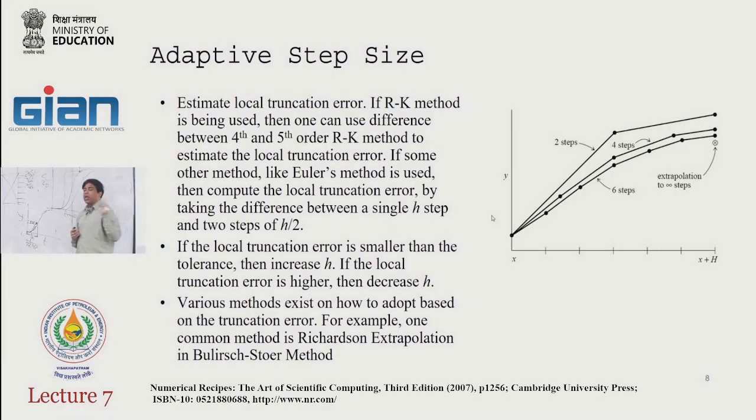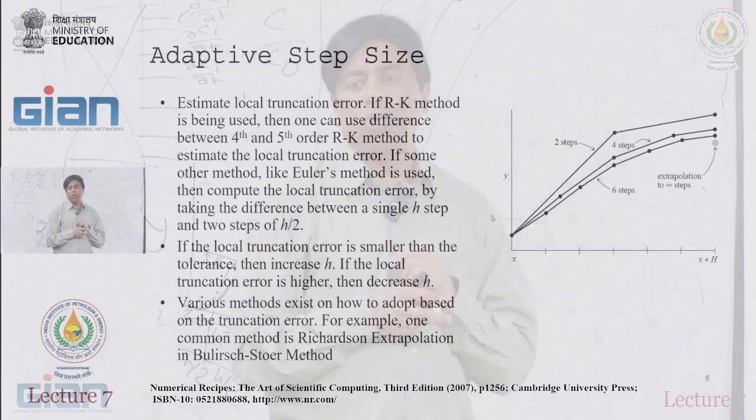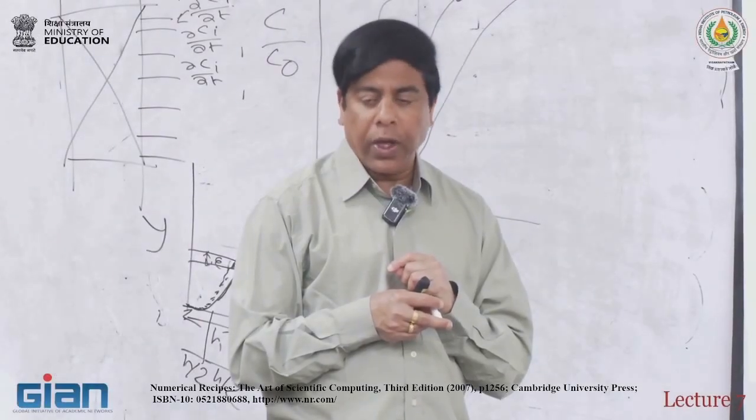So once again, the takeaway message from this slide is that for adsorption system simulation, especially when you have a steep breakthrough curve like that, an adaptive solver is absolutely critical for you to have success.